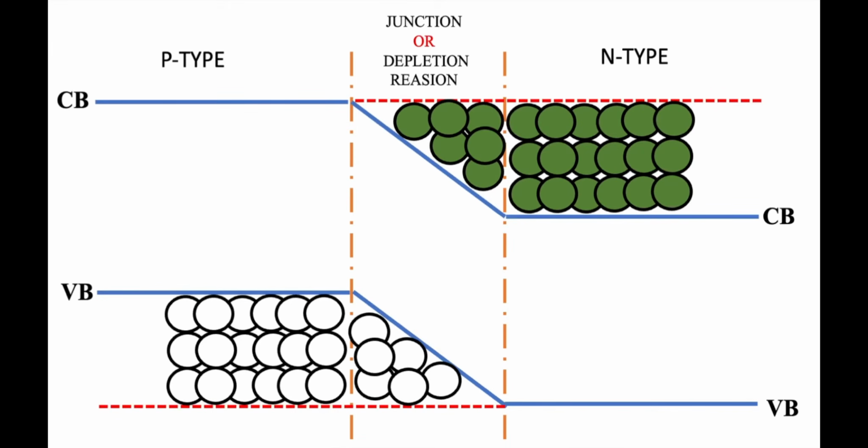Okay, what will happen at initial voltage or for a low current? Then only a few electrons recombine with a few holes. Due to this, spontaneous emission will be seen, and the entire setup works as an LED, a light emitting diode.